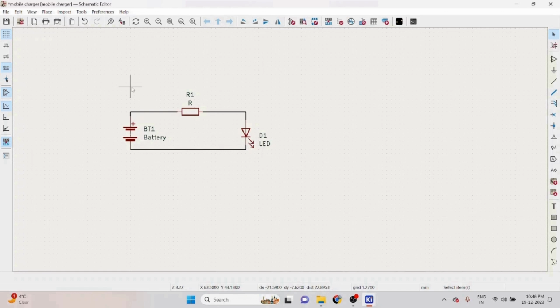I prefer to leave the grid on so I can see where I am placing the components and how they connect to each other. But this tool will help you turn it off in case you want to snap a screenshot or perhaps you just want a closer look at the schematic. Then these three buttons that we now have will assist in adjusting the document units. You can use the millimeter or inch, whatever you want. Additionally, we observe that has been reflected at the bottom here. I like to use millimeters, so in the upcoming videos, every measurement and computation will be made in millimeters.